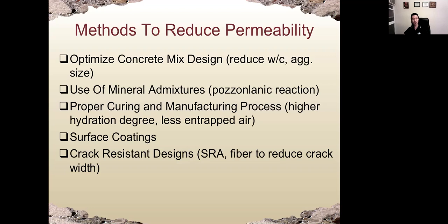Better curing, longer curing, is also beneficial to reduce the permeability. If we can increase the hydration degree, and if we can reduce the entrapped air, we can also reduce the permeability. If we can use surface coating, of course, permeability will be reduced.